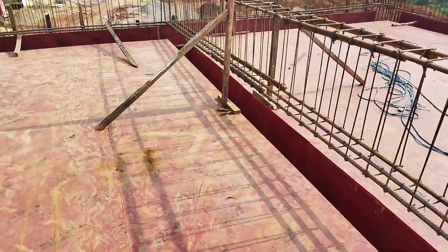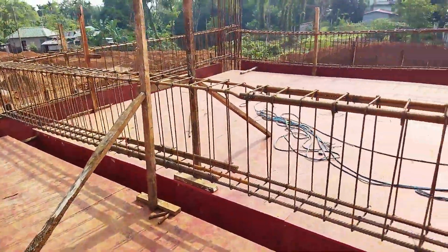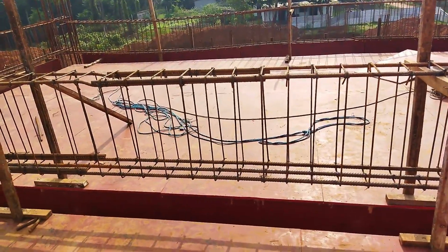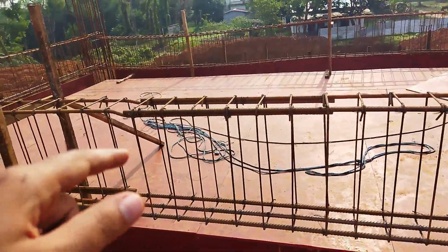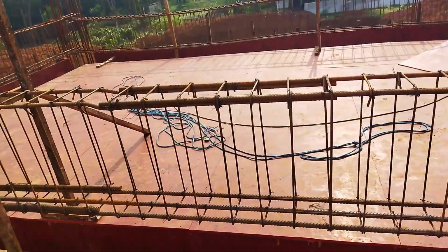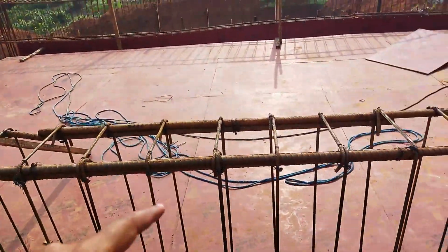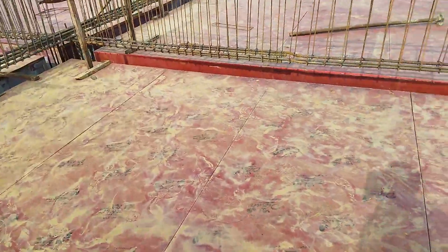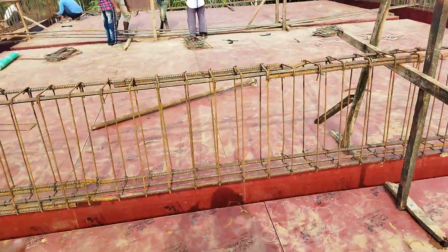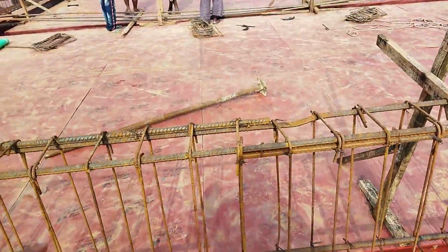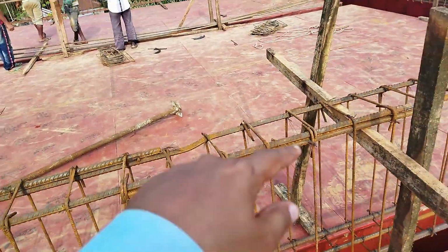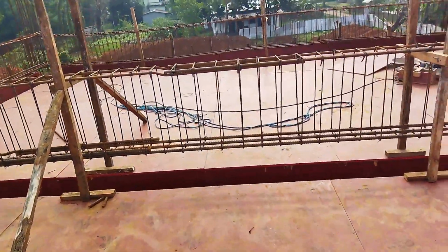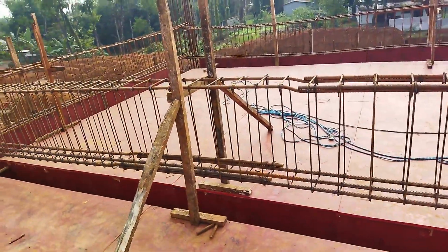And as you know, if you see the structural analysis diagram, the moment is minimum at the center for the top fiber. So the lapping is provided at the center for the top reinforcement. And if there are more than 2 rebars, it can be given in a staggered way as well. One is like this and one starts from here. So a staggered arrangement can also be done if you have more than 2 rebars in the case of top reinforcement.